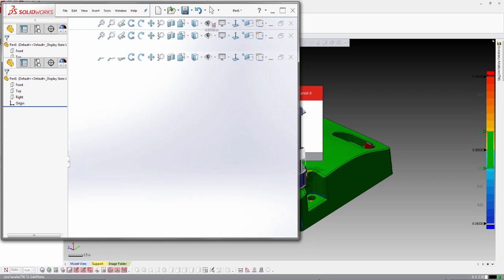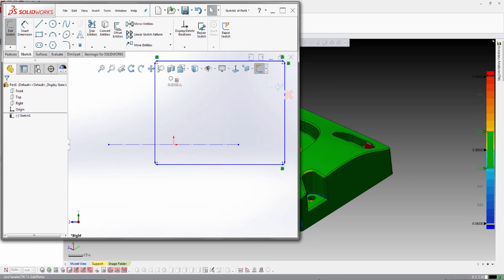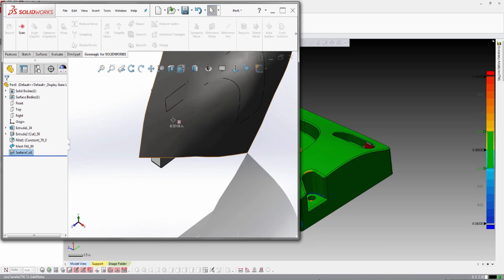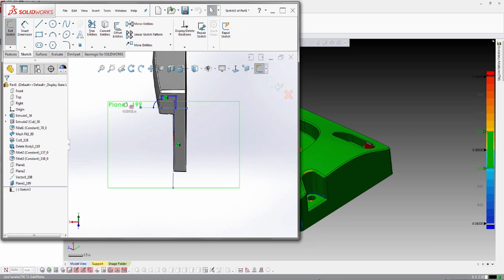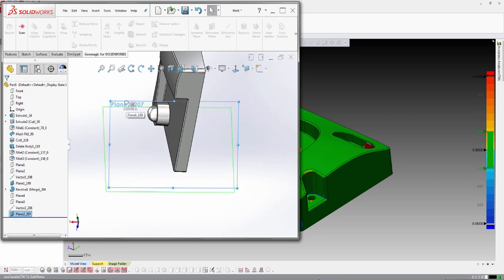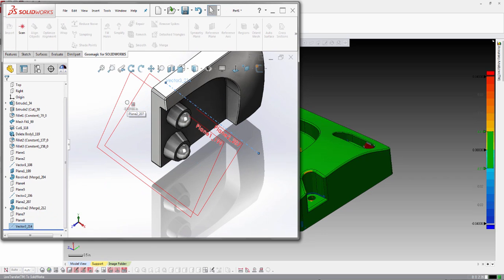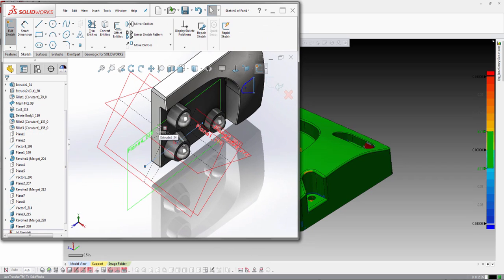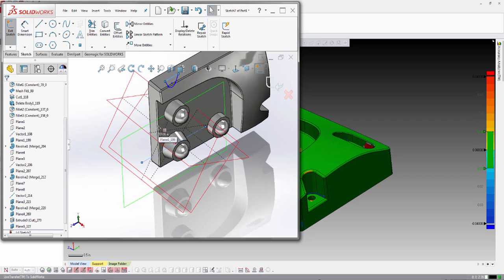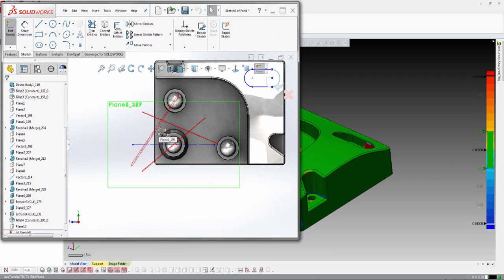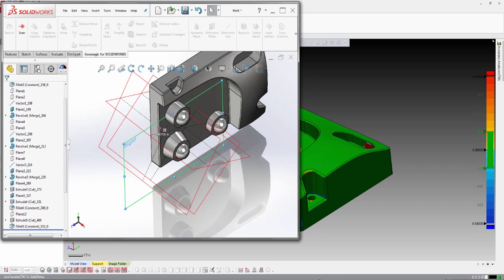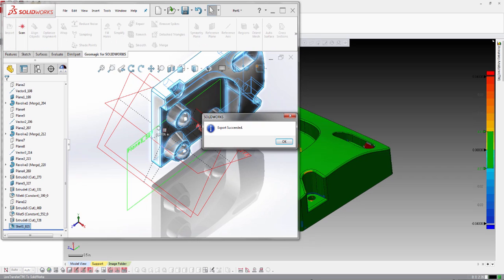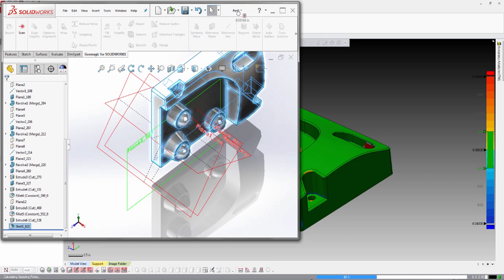Okay, so SolidWorks is launched, and then the DesignX software starts sending the features over one by one. The sketch and the extrusion with draft, the pocket that was cut out, the surface that was used as a cutting tool and then deleted, the revolve feature, the revolve sketch, the last revolve sketch. I think we dimensioned that up. There's a couple of dimensions that are showing up. We added a couple of cuts, some fillets, and I believe the slot feature was fully dimensioned, fully constrained. So that has all the constraints built in. The final cut and then the final shell of the model was added to finish the entire process.